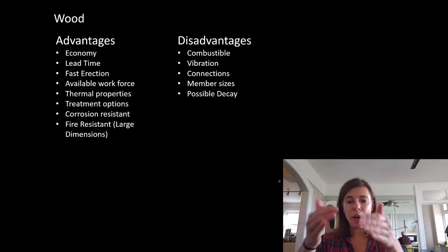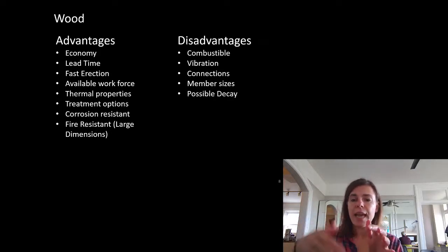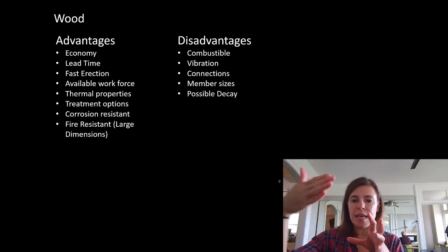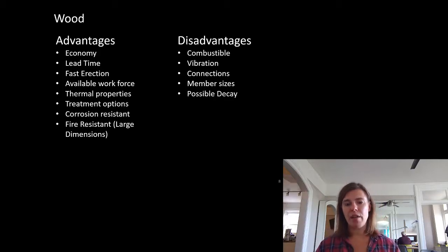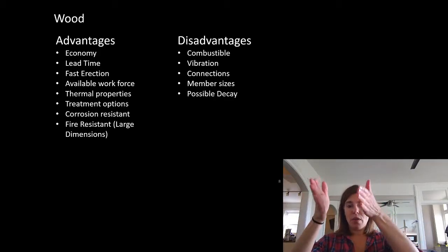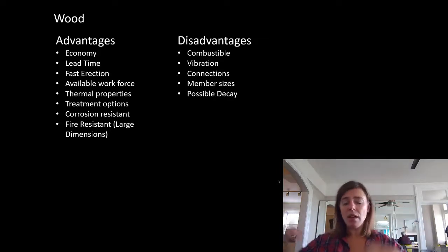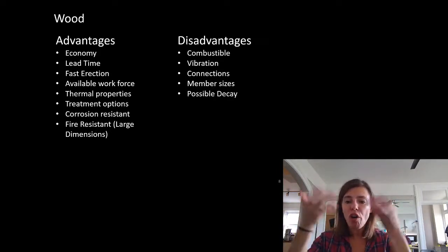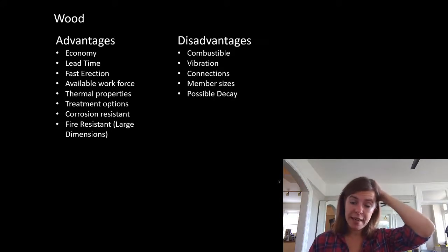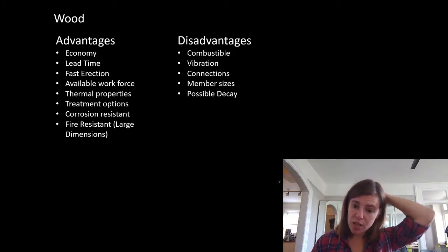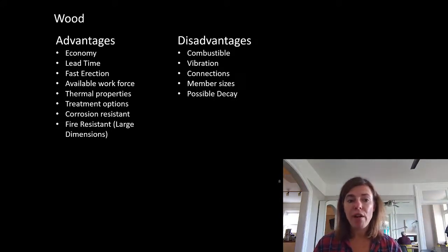The heat bounces off each of the surfaces and helps contain that heat and propagate the fire there. In mass timber, you have a big element here, or maybe just a big flat plate of wood where it's hard to get that originally ignited. So there are two advantages there in the fire resistance of large wood elements.